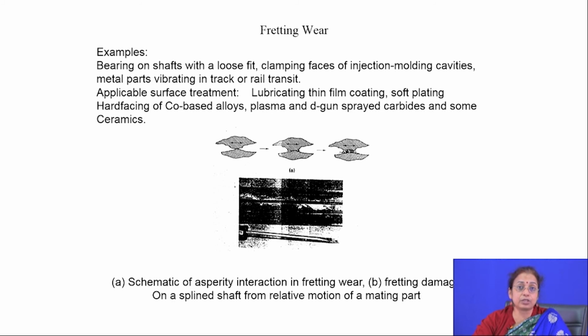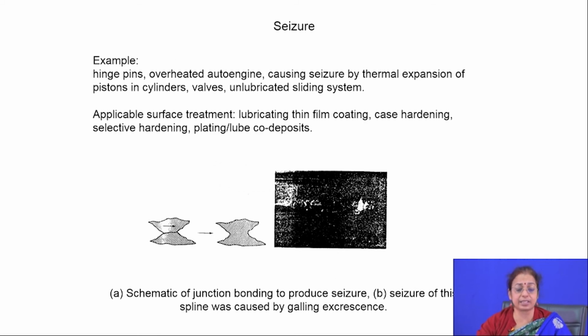Their hardness difference should be as small as possible, and the lower the surface energy differences, the higher the probability of adhesive failure or adhesive wear to occur. So, in simple adhesive wear, the wear initiates by adhesive bonding, and then depending on the hardness of the individual surfaces, the failure occurs.